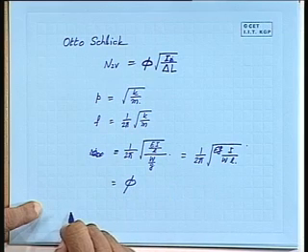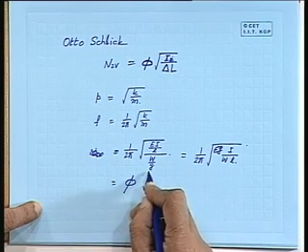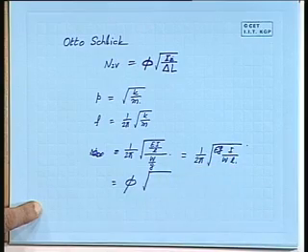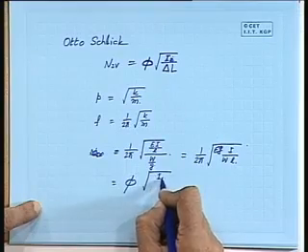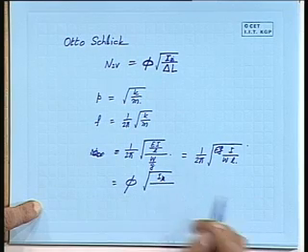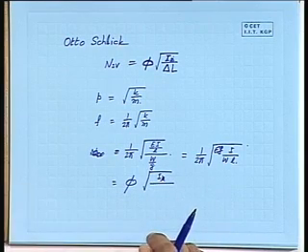Root Eg by 2 pi is phi, and I is the moment of inertia of the cross sectional area of the beam. Now if I assume that the beam is the ship girder, then the moment of inertia at the midship section is nothing but I midship. Okay.